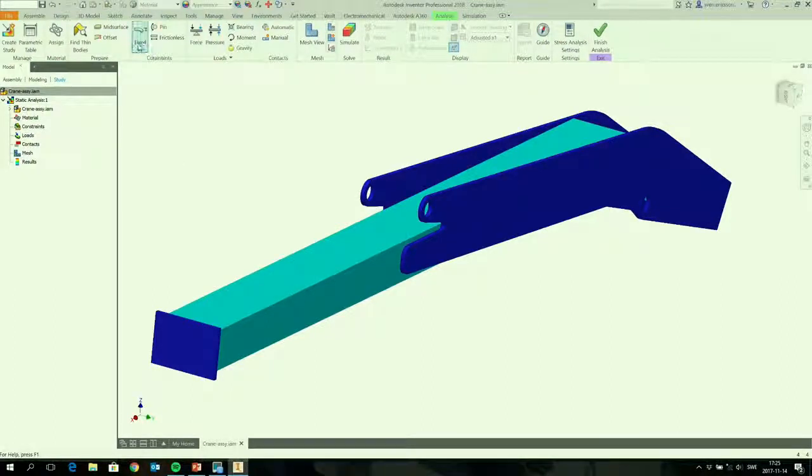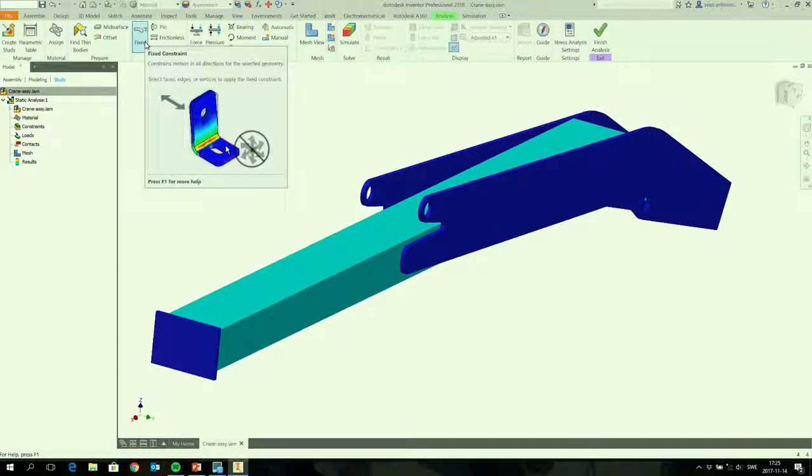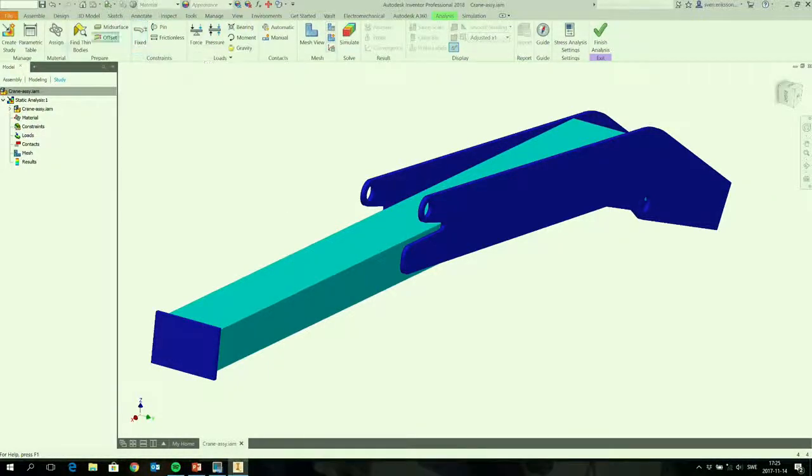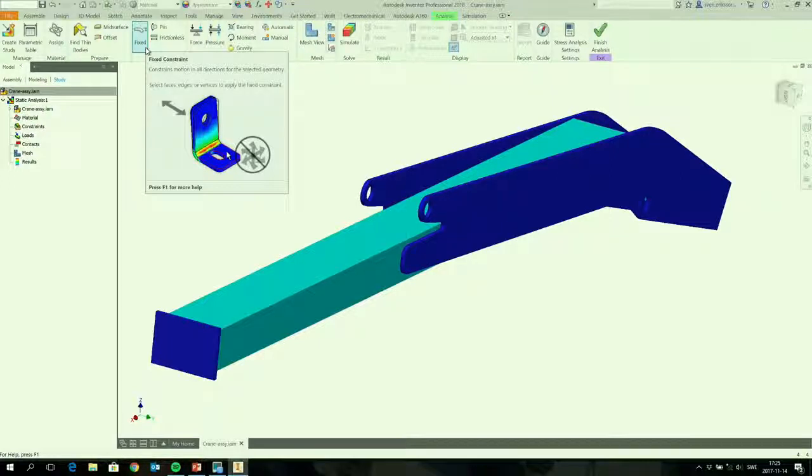So we come to the constraints, how to attach it to the environment. And to be honest, this is the part that you should pay attention to when you work with your own problem. I'd say that at least 50% of the failure is done in the boundary conditions. Often it goes higher. Often you can make any kind of failure on that one.